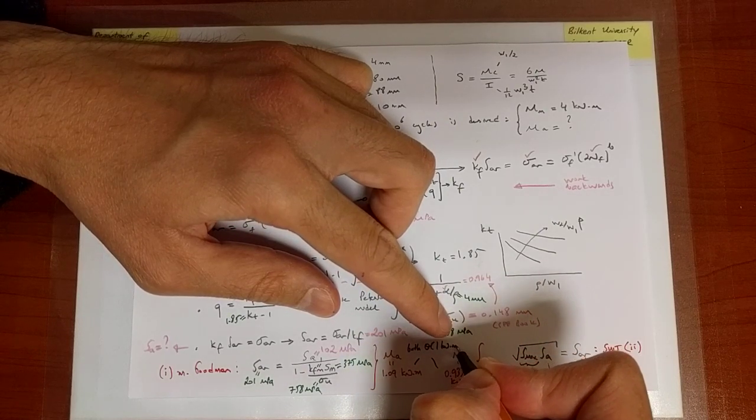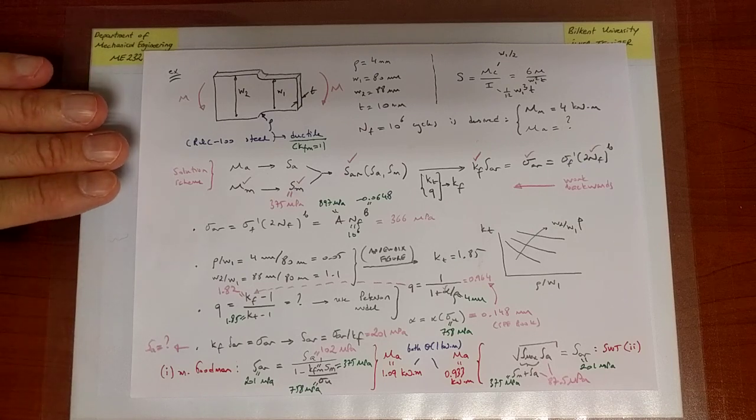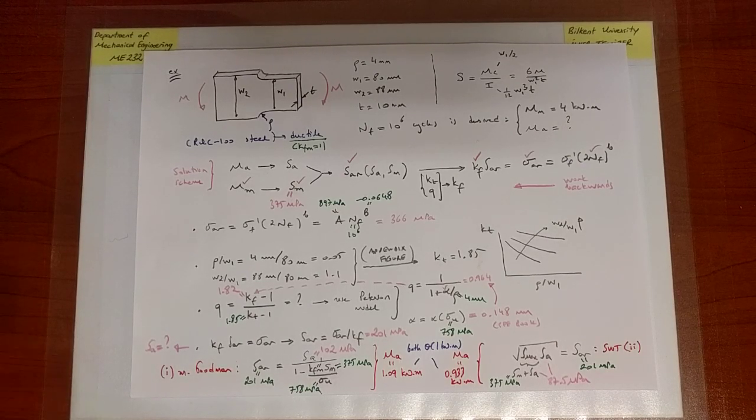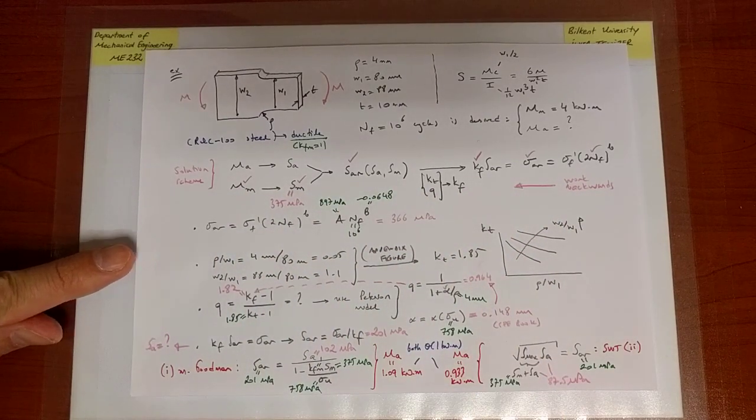So despite the fact that the models look very different, engineering-wise and to within probably a good safety factor which we did not have presently, they work just as fine. So you know that to a good reliability here, to the extent that we know that these models do work well, the maximum alternating bending moment we apply is 1 kilonewton meter. So again, I should highlight that the solution scheme should be clear in our minds, but of course for the details, for the figures, for the equations, etc., we always have to refer to references, but the solution scheme should be absolutely clear in our minds.